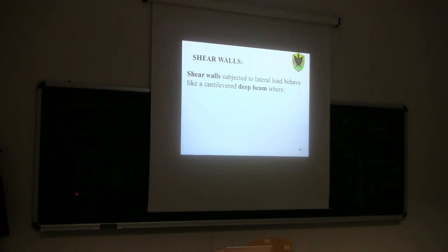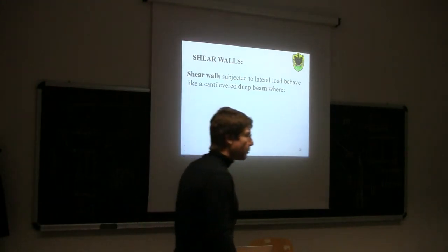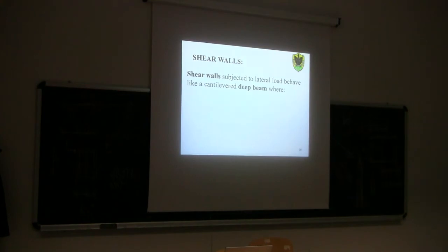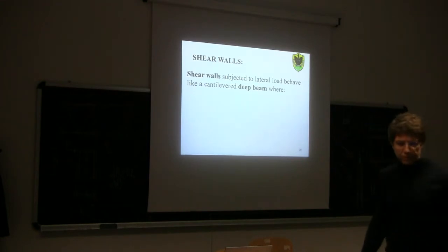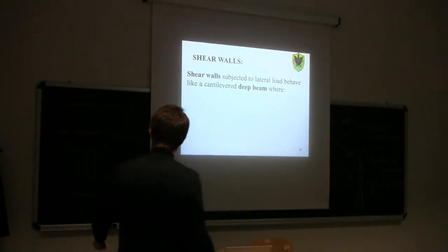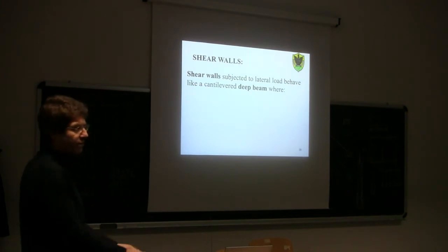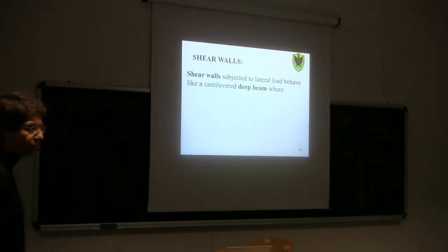So, suppose for a moment this connection was rigid. If this connection was rigid, a section like this, how can it resist bending moment? Suppose that you are back 2 or 3 years ago, doing an exam in mechanics of materials, and you are asked to calculate the stress distribution of a cross-section like this, subjected to bending moment and then shear. How would you solve this problem? Of course, in that case, they would have told you that this connection is not made by glue. It's like if there was a connection without any discontinuity.